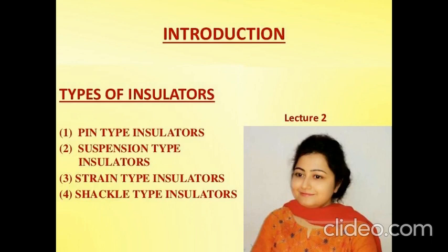And the span between the two towers is dependent on the allowable sag in the line. Now the insulators are designed and manufactured for a certain voltage range, and the maximum voltage per insulator is about 33 kilovolt. Now we describe the types and characteristics of line insulators.